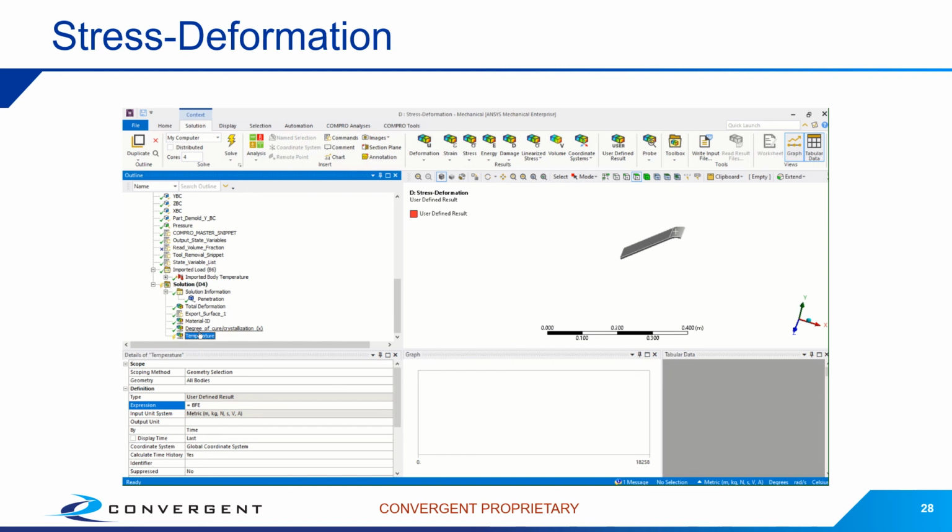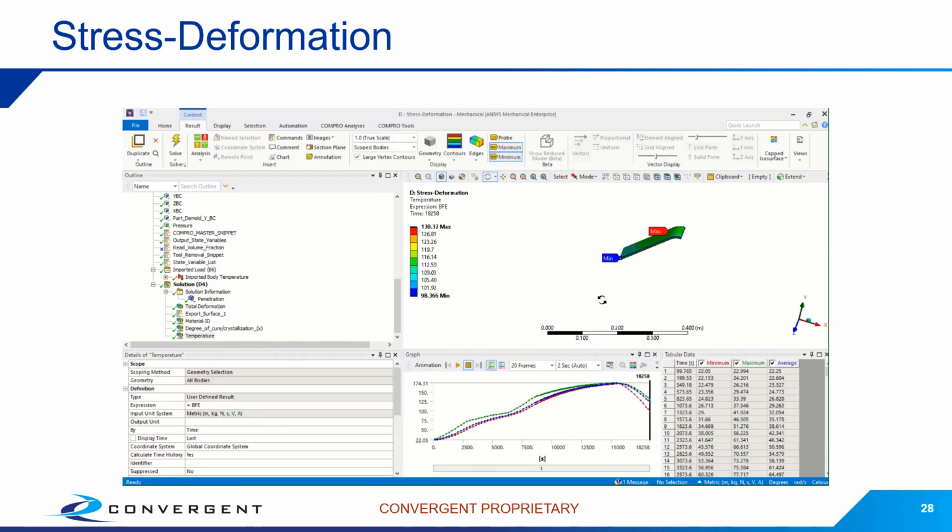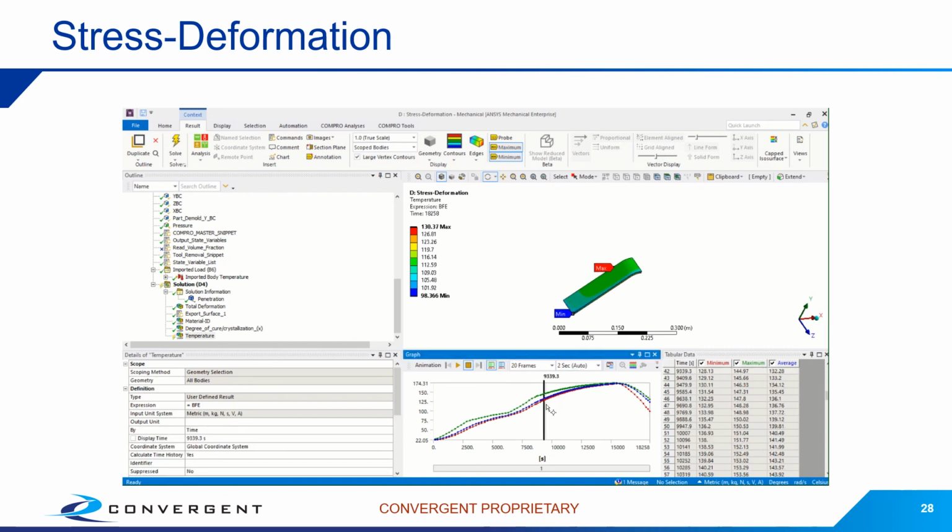So we can see clearly that there are thermal gradients in our part that are undesired, quite big ones, from 90 to 130 at the end of the cycle. We can see that there are various issues during the cure cycle as well. We can see that there's various issues around thermal lag, et cetera, et cetera. So yeah, we have many issues to work out on this part.